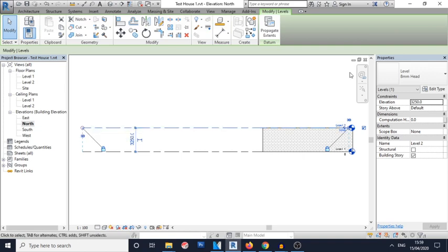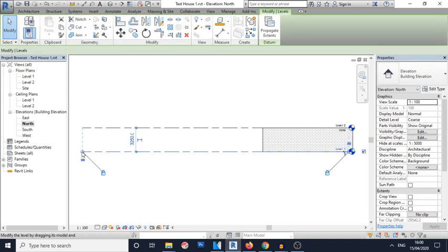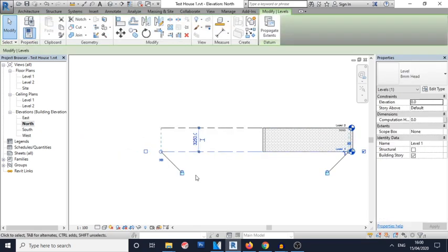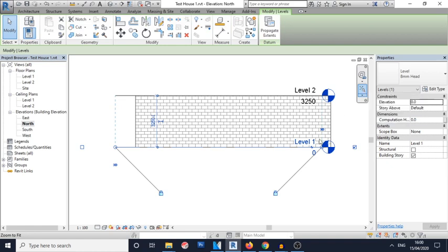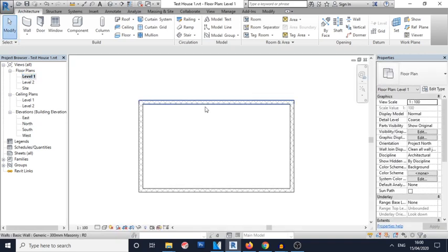And what I want to do is bring them in. So what you should see is I'm just clicking inside this circle at the end of the line and then dragging it towards the wall. Now when I go to zoom to fit, we have a much tidier presentation. And then we'll go back to level 1 by selecting level 1 on the left side of the views. And here we are back to our plan.